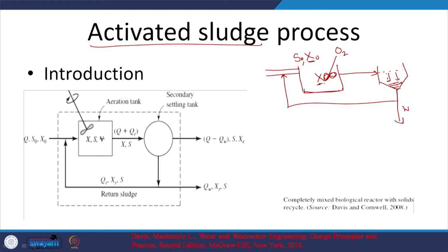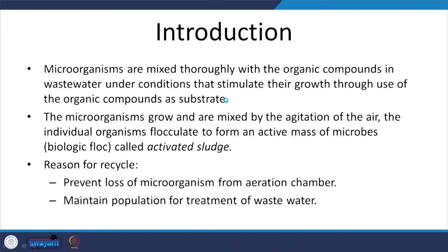or you can recycle that, R for recycle. Okay, I should not draw it here, maybe I should draw it right here. I can recycle it such that the concentration of the microorganisms in this tank, where the actual reaction and degradation takes place, is pretty high. So, that is why we call that activated sludge, as in this sludge which has the microbes is reused, the activated sludge process. Again, that is the relevant schematic out here. Let us move on. I believe we already looked at this.